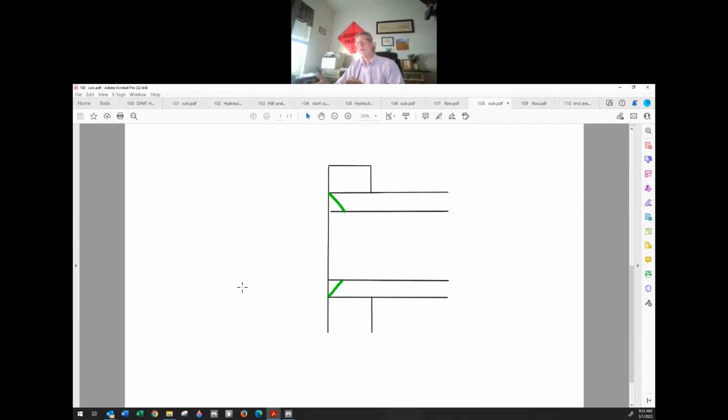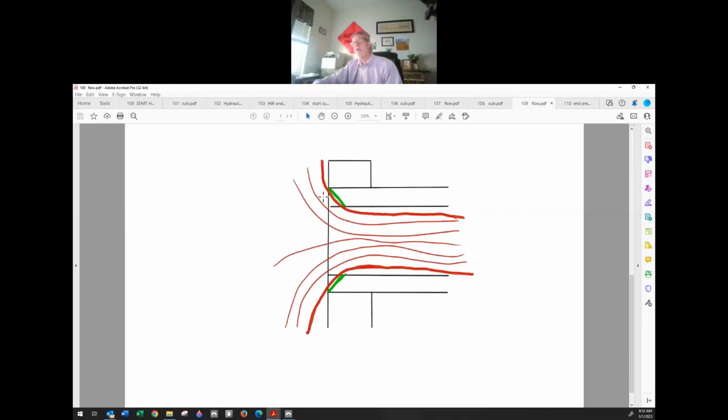And think about the guy in construction. He's not going to get out there with a protractor. So make it 45 degrees and he can guess what that is and get that in for you. So you can bevel these. And then what happens is that bubble goes away and the water just hugs the pipe and you can get a little more flow through the pipe. So if your head water is going up a little too high and you need it to come down just a little bit, you might be able to do that as opposed to going up and adding another pipe beside it or going up another pipe size or so.